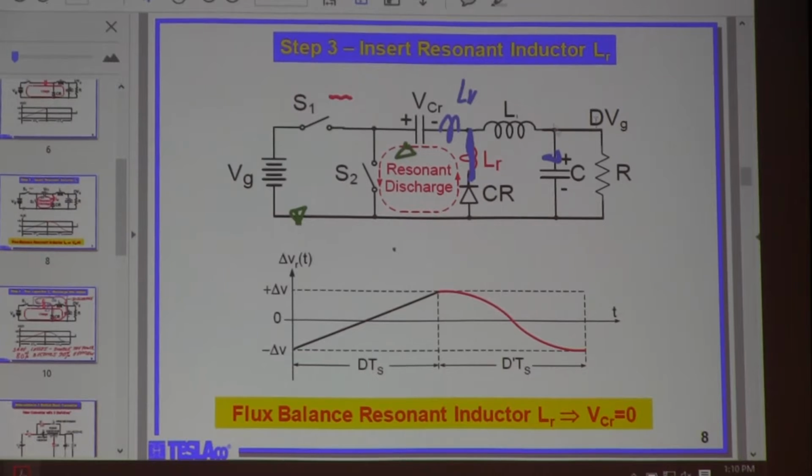in that version of the converter. But guess what? Its beauty is in the simplicity, right? This final version doesn't have to have an external resonant inductor. It works only on its own leakage inductance, absorbing it, and at the same time you don't have to build it. It's part of the circuit, and it doesn't have a jump, so there are no losses. You see here, this is smooth.